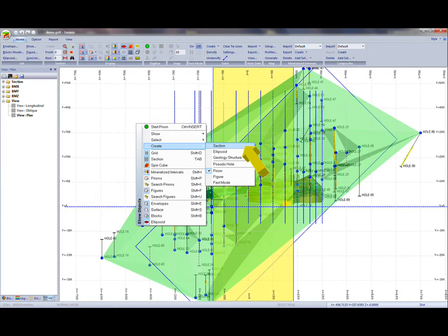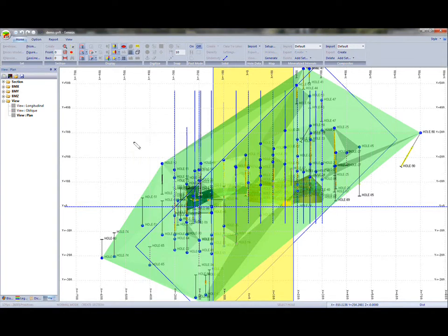Section creation, tracing. It is possible to create a section perpendicular to the current section by selecting Create, Create Section from the General Context menu. The mouse pointer becomes your pencil. Click the central position for the desired section and drag your mouse to draw a framework of the new section. The infinite line indicates the vantage direction for the section.